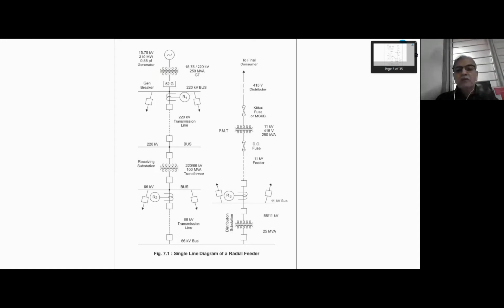You cannot go for versatile relays. And obviously, when you use a relay, one cannot pass the large current of a transmission line through the relay. So one needs a CT, current transformer. If it's a voltage operated relay, then you need a PT, and a relay cannot interrupt the fault current. Therefore, one needs the circuit breaker.